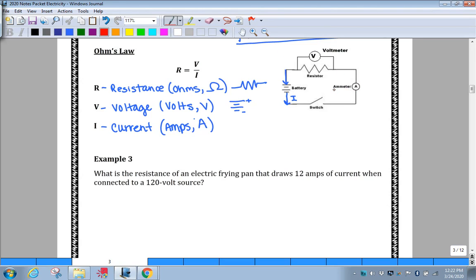And I just want to point out two things on our picture over here. Over here on the right side is our ammeter. Ammeter measures current for the circuit. And the way this is connected, this is called a series connection, because the wires go directly into the ammeter and come out of the ammeter. It's inside the loop of the overall circuit, where the voltmeter, which measures voltage, is connected in parallel. A parallel connection for a meter, you're going to have separate branches for that meter going across whatever device you're going to measure. So the series connection, the meter's in the big loop.